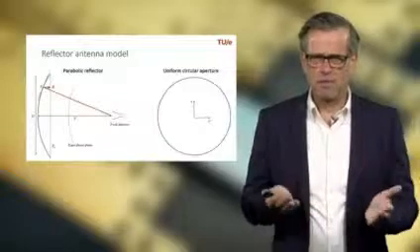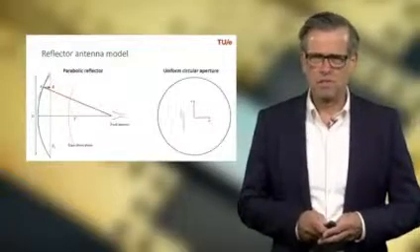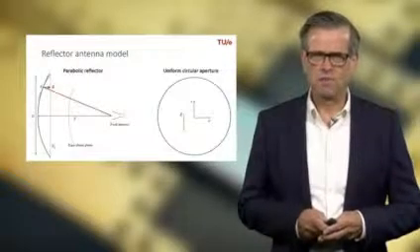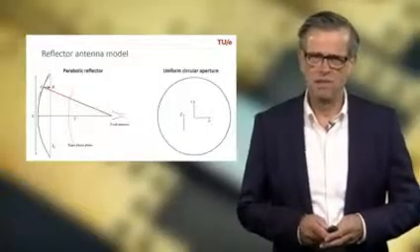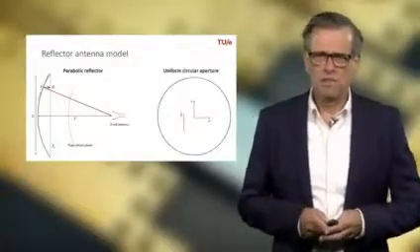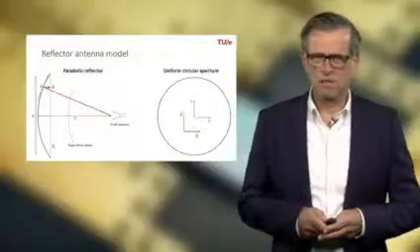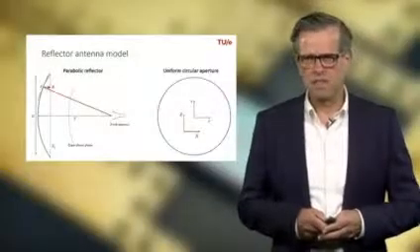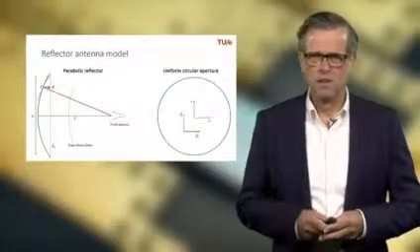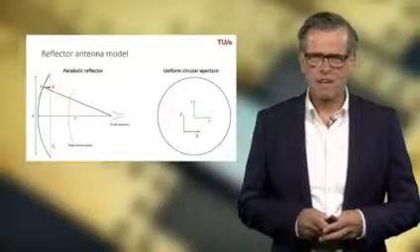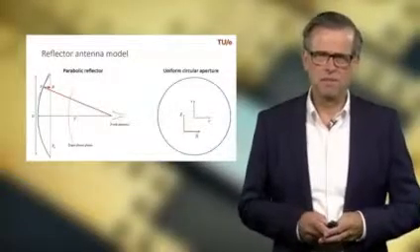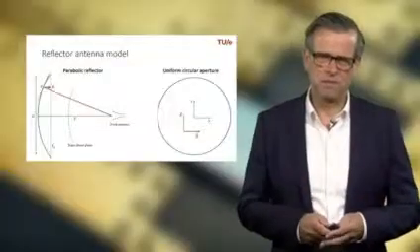And within this aperture surface, we assume that the electric field will be oriented in the x direction, and the associated H field will be directed in the y direction, as indicated here by the red arrow. So this is the model that we're going to use in our recipe that we derived in order to calculate the far field.